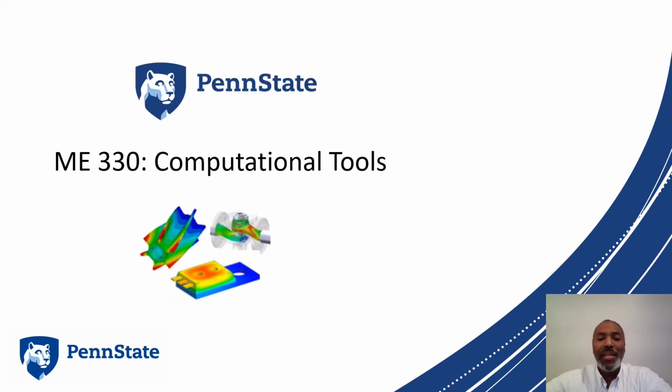Alrighty, folks. Once again, thank you for participating. Thanks for joining in and viewing. Hopefully you've learned a good bit about how SolidWorks implements contact conditions, a little bit about how those search algorithms and how those penetration algorithms work, the penalty method and Lagrangian methods. Most importantly, we have the three types of definition: allowed penetration, no penetration, and bonded that we can deal with, because we have to know how those operate, because those determine whether or not our model is behaving physically.